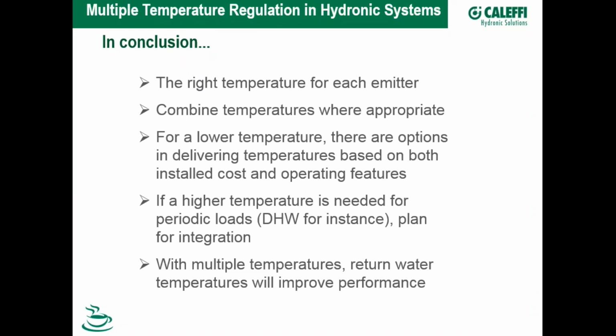Let's select the heating curve that drops the water temperature down to keep the heating system in balance with the heat load of the building so that the call is always there. Because the end result is, if my thermostats are ever satisfied, that means that I'm putting a little bit more heat into the building than it actually needs, which means I could probably drop my water temperature a little bit lower.